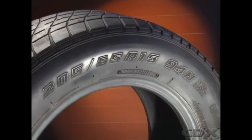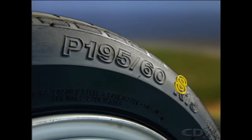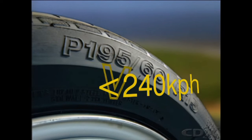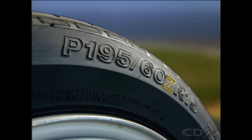Information on tire aspect ratio is now included in the sidewall marking, together with the type of construction and the speed rating. The speed rating of the tire is given by the letter code, which indicates maximum recommended speed for that tire. Common symbols for passenger car tires include S for up to 110 miles per hour or up to 180 kilometers per hour, H up to 130 miles per hour or up to 210 kilometers per hour, V up to 150 miles per hour or up to 240 kilometers per hour, and Z for over 150 miles per hour or over 240 kilometers per hour.